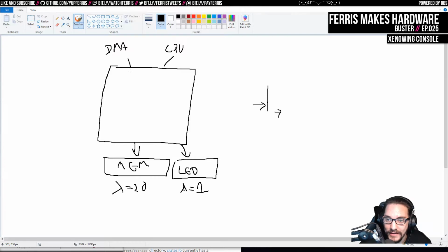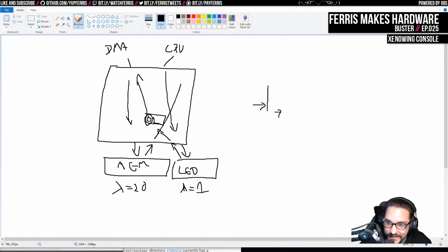So let's say the DMA issues a read to the memory, and it pushes a 0 into this FIFO. And then let's say before this data comes back, the CPU, maybe on the next cycle, issues a read to the LED thing. And so that's going to put a 1 into the FIFO. Then what happens is the LED comes back with its data on the next cycle. And that's actually bad, because now this incoming data is going to pair with this master, which is the first thing that comes out of the FIFO, and it's going to send its data here, and then when the memory comes back with its data, it's going to send its data here. And so now both of these units got the wrong data.